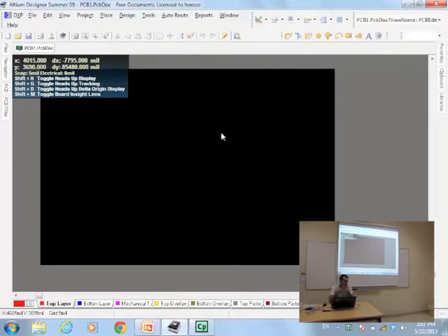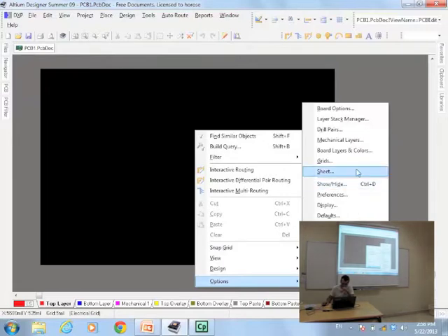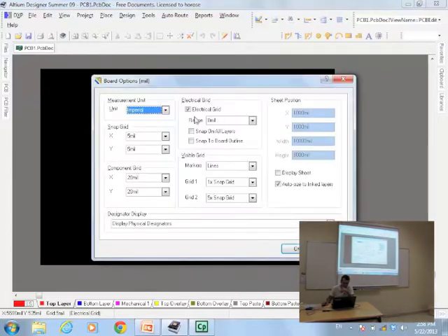This will be generated and built on a real material, so measurements should match each other. Measurements are very important. Even microns on PCBs are important. Altium is an American software, so its default is imperial. It works with inches and mils and these things. I don't want it, so I changed it back to metric.